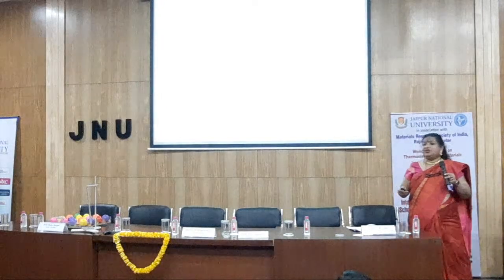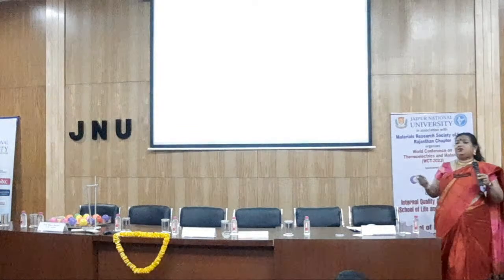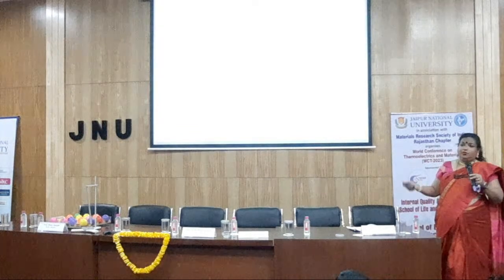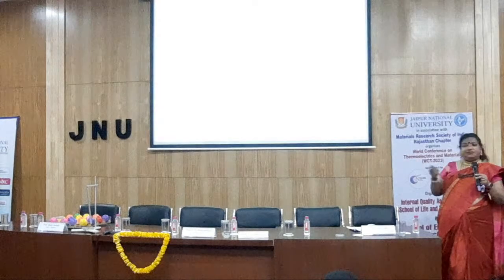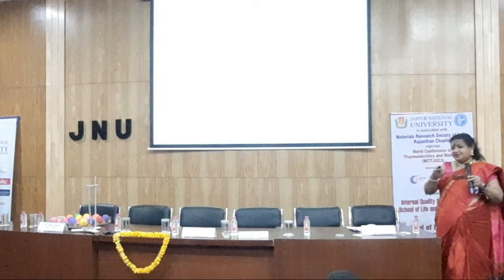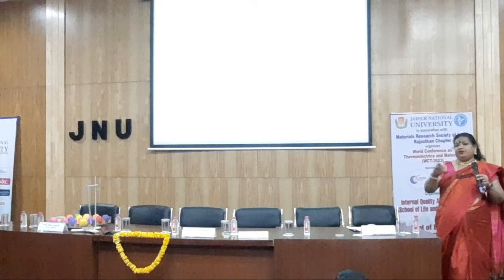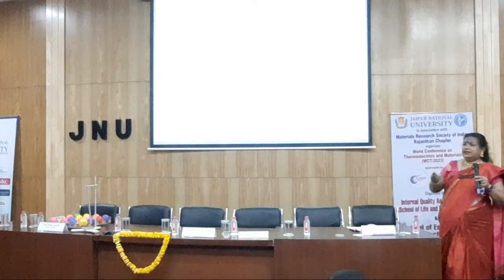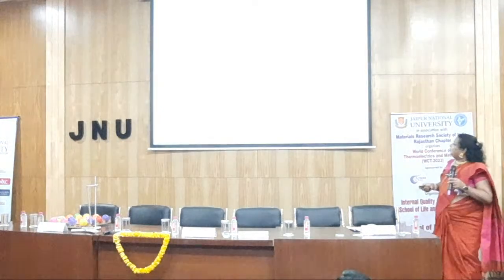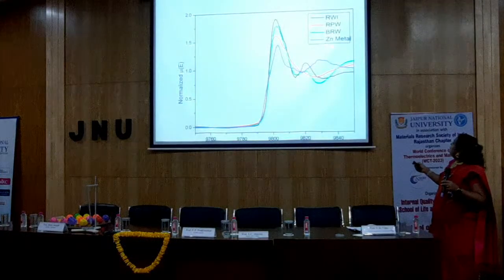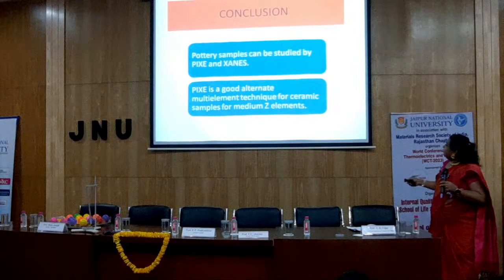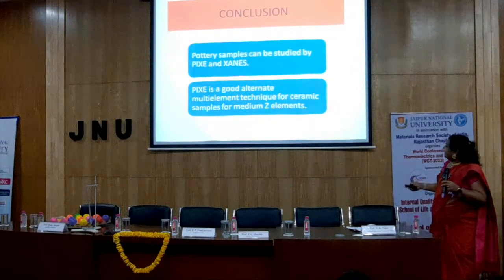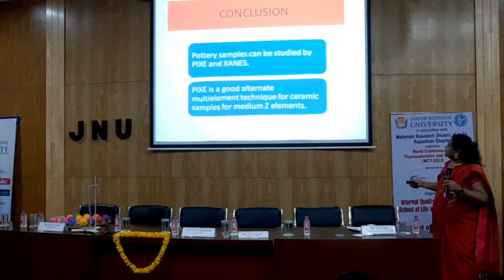XRF cannot measure oxidation states. It can only measure whether Fe is there or not. Whereas XANES and EXAFS can measure the shift. It can tell you whether it is 2+ or 3+. So that is required for many material analyses. Next. Here again you have it for zinc. Next. So the conclusion is it can be studied with PIXE and XANES, and it is a good alternative.